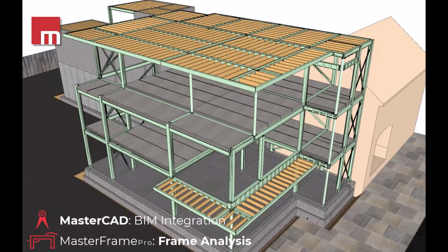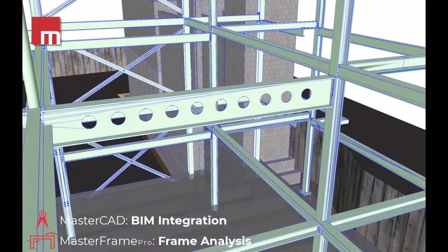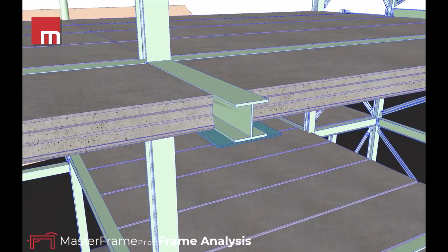And if we go into more detail on the steel frame, the frame uses a mixture of UBs, UCs, hollow sections, angles, channels, and flats. And we can model steel beams with web openings, and in this case, circular web openings in MasterFrame as well, with regular centres. We can also design compound sections with top or bottom plates, and in this case, bottom plates to support the precast concrete slabs.